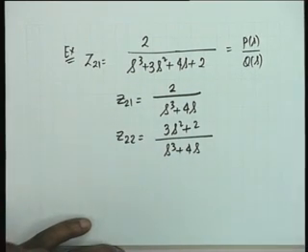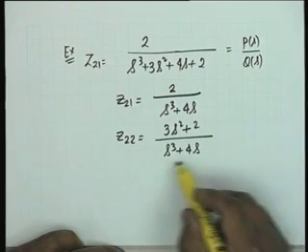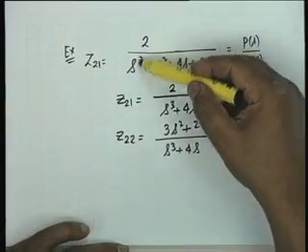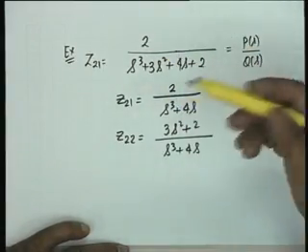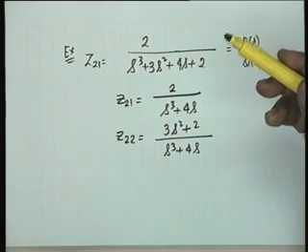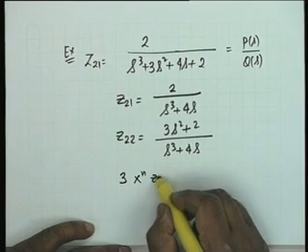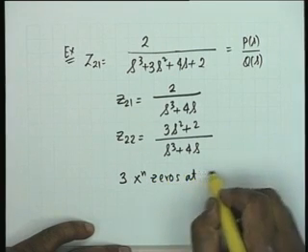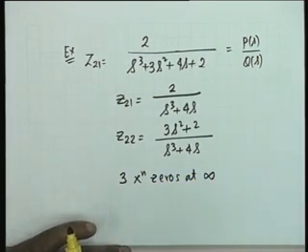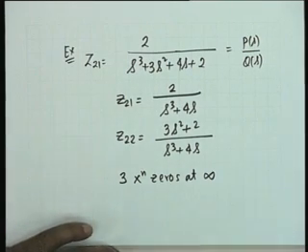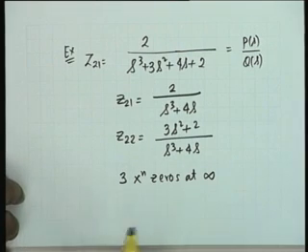And the problem now is to realize Z22 in such a manner that the transmission zeros are realized. The transmission zeros, if you look at this function or this function, are 3 in number, and they are all at infinity. 3 transmission zeros at infinity. And we have now to guess the structure as to how 3 transmission zeros can be realized.